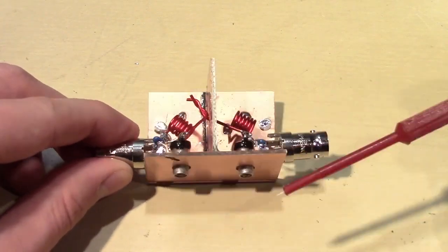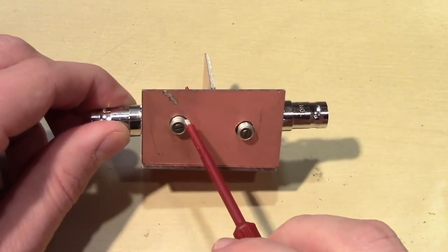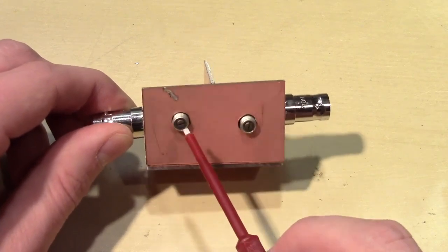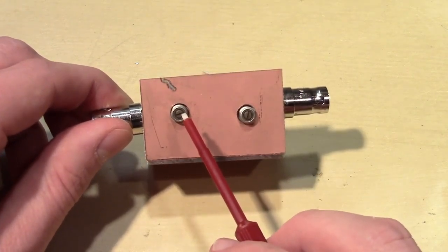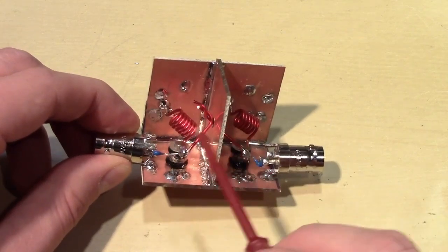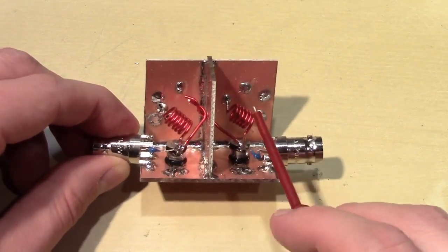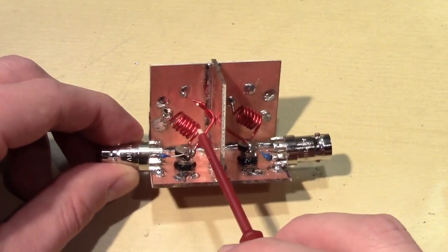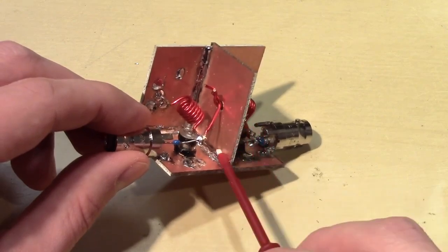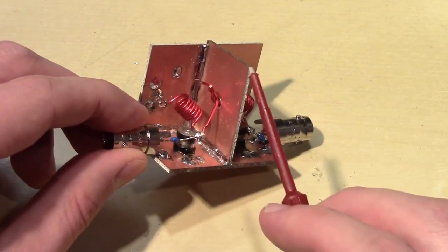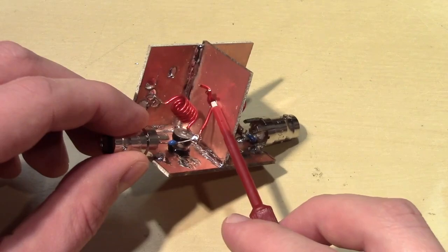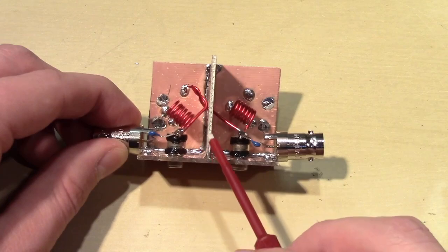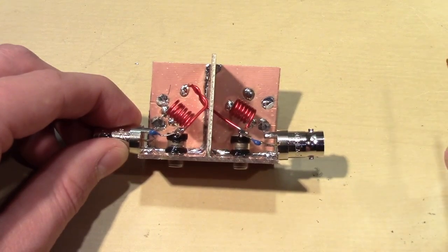So this is the exact same filter. I'm using some piston trim caps here instead of the air variable caps I had in the other filter. They're just a little easier to tweak the filter with because they're multi-turn. But otherwise, the filter is exactly the same, using the same inductors, same coupling capacitors. I've got my little 2-wire coupling capacitor here, you can see. But I've added just a bit of shielding here, and this is built out of some scrap PCB that I cut up. I've drilled a little hole through the shield to pass that coupling capacitor through. But just this little bit of shielding can make all the difference in the world.